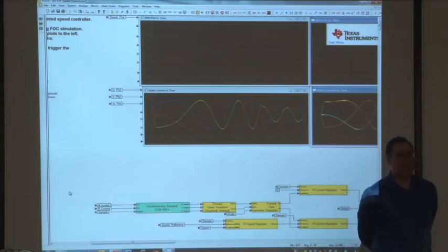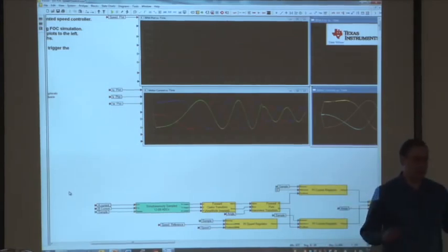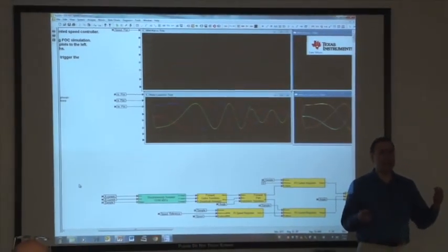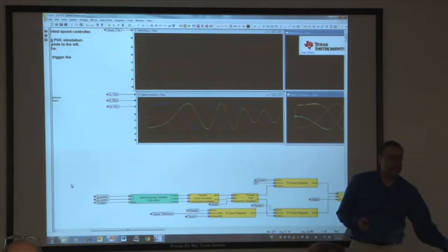Uh-oh. Probably several people made some mistakes. In most cases, you can go back, and it's just because either there's an unused connection somewhere, or one of your connection variables is misspelled or not the same that you dragged over somewhere else.